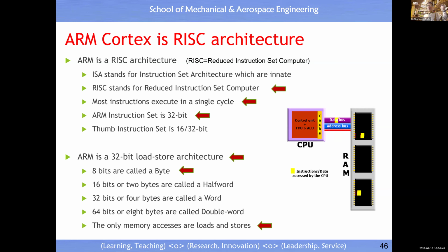And to communicate 1 bit, you need to have the support of 1 physical line, 1 cable, 1 lane. If we want to communicate 8 bits, then we need 8 lanes. Or eventually, with 1 lane, you communicate 1 bit, and another bit is shifted in a shift register, to do the shifting, and you put them together.